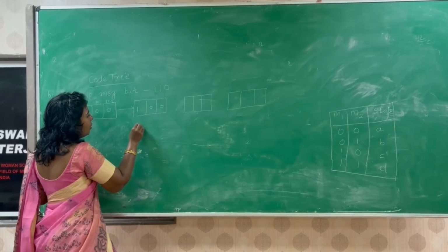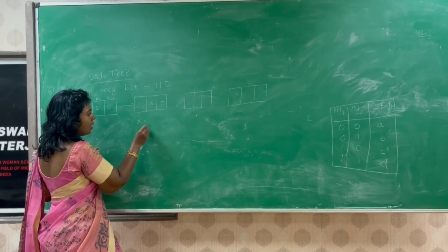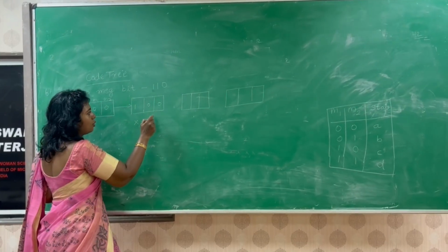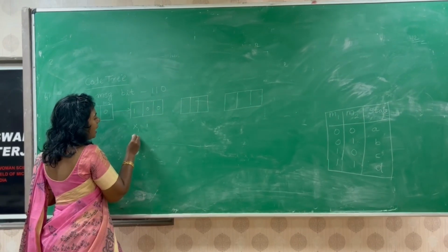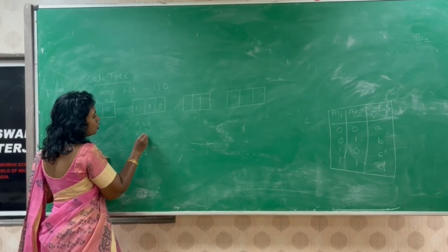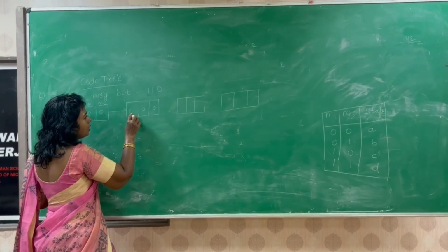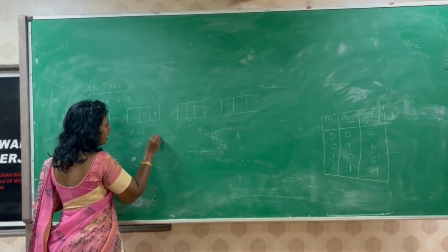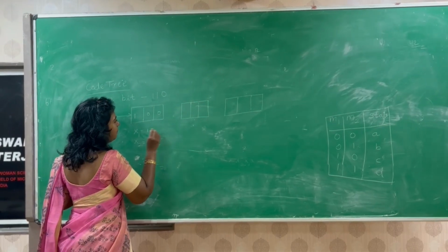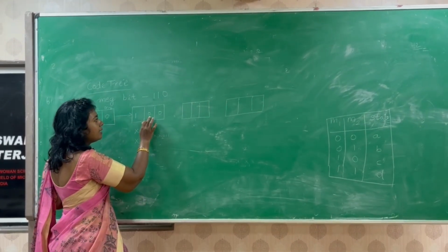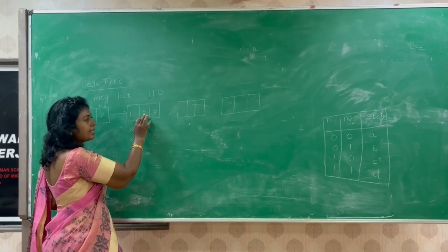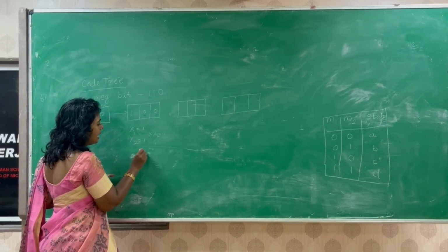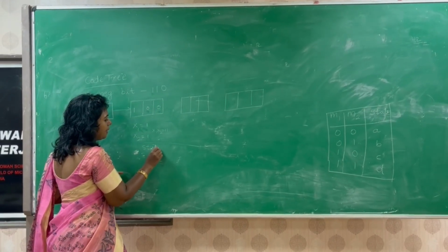Okay. So now, what is the output X1? X1, I told you, is M0 XOR M1 XOR M2, which is 1. And output X2 is M0 XOR M2, which is also 1. So output X1, X2 is 1, 1 here. And the state depends upon the content of registers M1 and M2. Here the content of the registers is 0, 0, so the state is A.